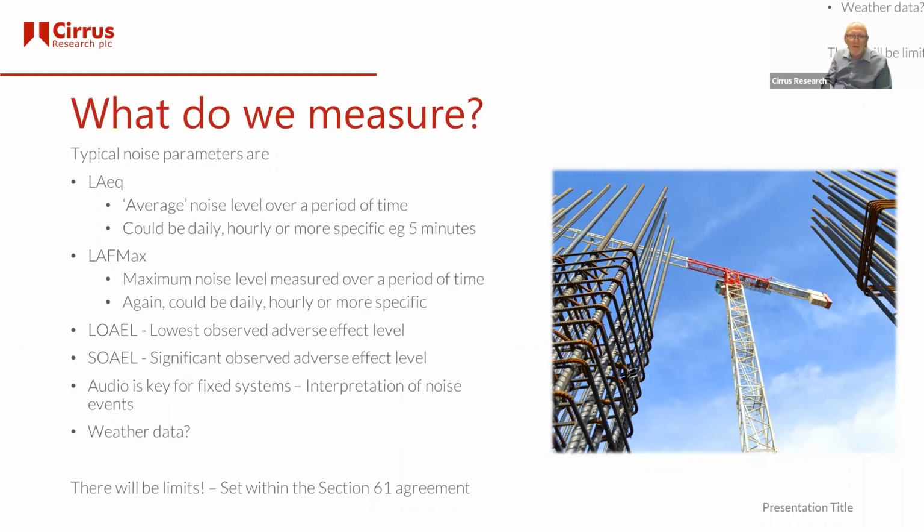In general, we measure the LAeq, the A-weighted continuous equivalent sound pressure level, or in inverted commas, average noise level over a specific period of time. So we're not interested in what's happening second by second, we're interested in an average over a period of time.